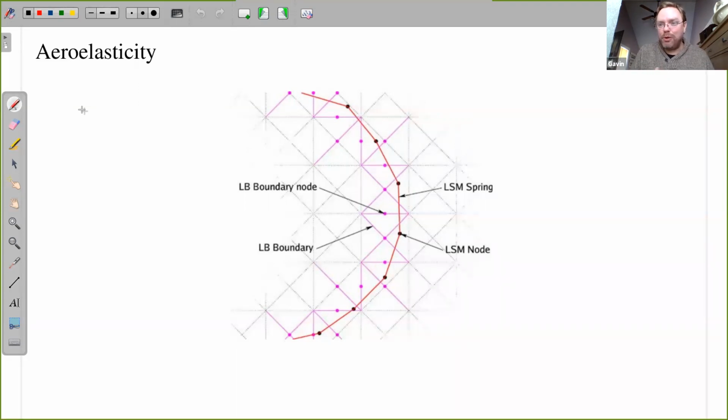In lattice Boltzmann, particles on an atomic length scale are basically just moving around, bouncing into each other. And so what the lattice Boltzmann does on a more mesoscopic scale is it has these particle distribution functions that propagate on a lattice, and then when they hit nodes on the lattice, they collide, and then they settle towards equilibrium, and then propagate on. So it's this propagation and collision, which is very similar to what happens on a microscopic scale.